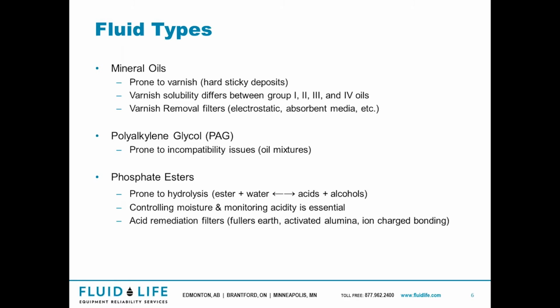A lot of these, though, are replacing the old mineral oils these days, and so they're prone to incompatibility issues. Replacing a mineral oil with a PAG can run into all kinds of problems, and so you definitely need to be talking to your oil supplier and the lab to make sure that you're not going to run into any of these issues if you're doing a switch.